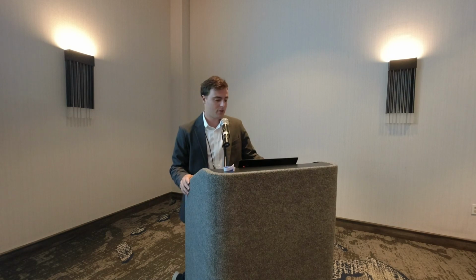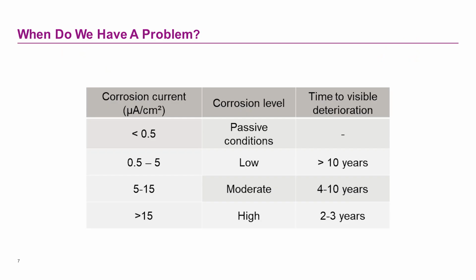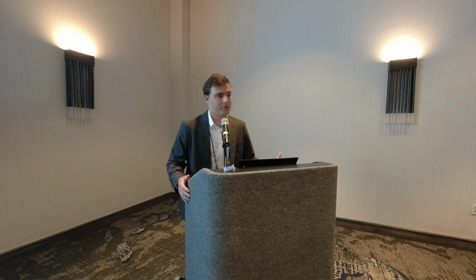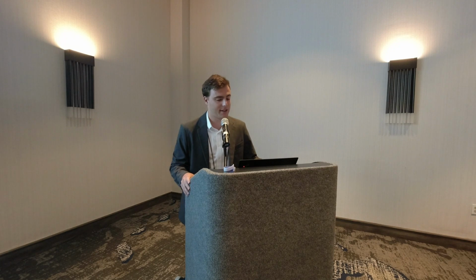And here's the kind of results you get. Our most useful result is corrosion current. It's presented here in microamps per centimeter squared. That's where the data is going to come from on the Galvapulse, but that can be converted to cross-sectional loss of steel. There are equations out there. You have to factor in environment and type of steel used. So once the testing is done, that can easily be calculated.